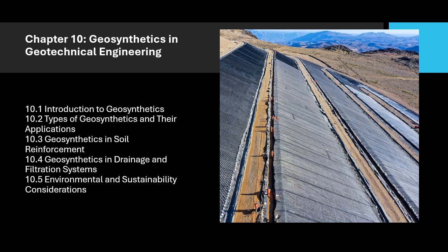10.3.1 Mechanisms of Soil Reinforcement with Geosynthetics. Geosynthetics reinforce soils by distributing applied loads across a broader area and improving the overall strength of the soil. The mechanisms through which geosynthetics enhance soil reinforcement include: 1. Tensile resistance.